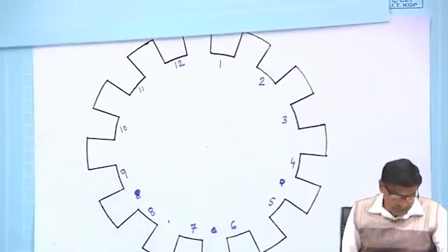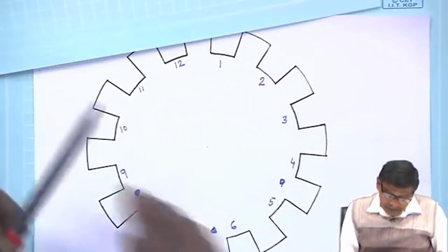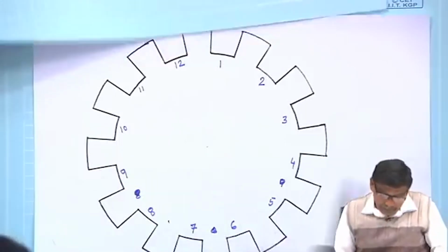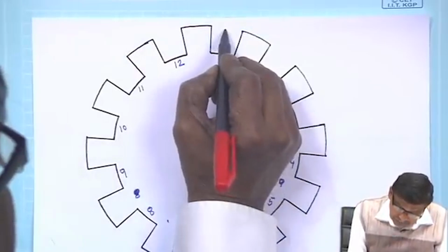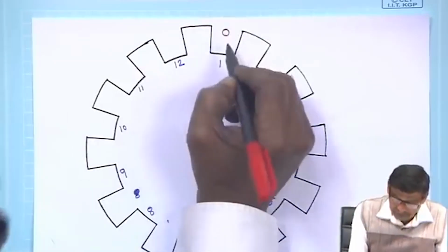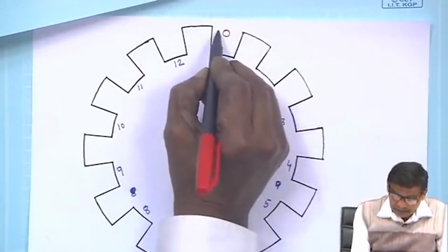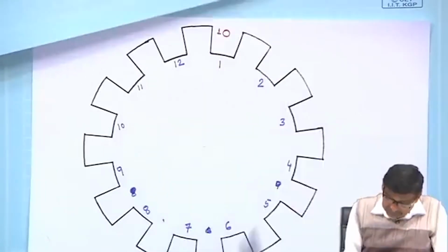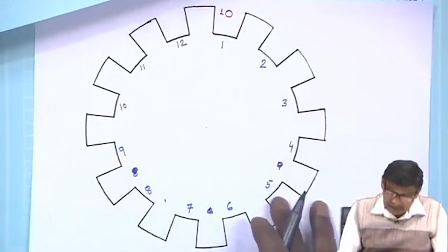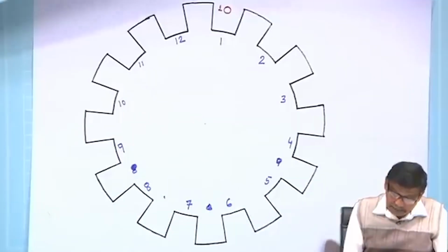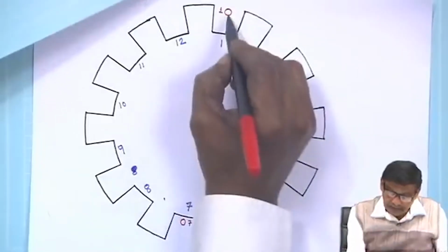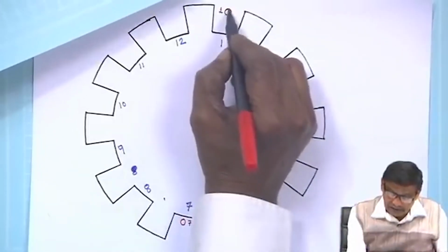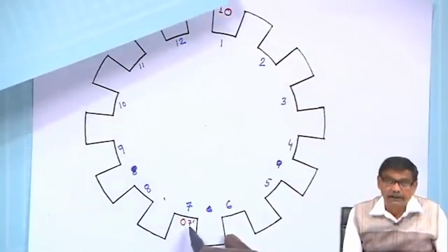Okay. So, the R phase coil winding I have shown you like this, but the actual disposition of the coils will be like this. You take the first coil and let me use the red wire to indicate R phase. So, it is 1 on the top, this is 1 and its return is at 7, diametrically opposite, because it is a 2 pole machine, it is 7 dashed. This is 1, not 10, 1 and this is 7 dashed.